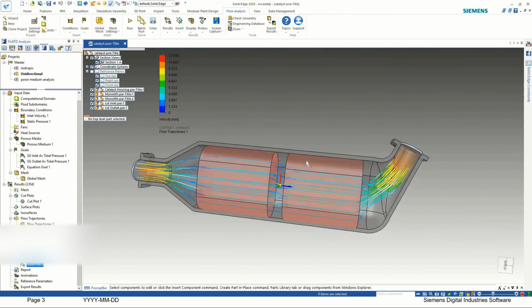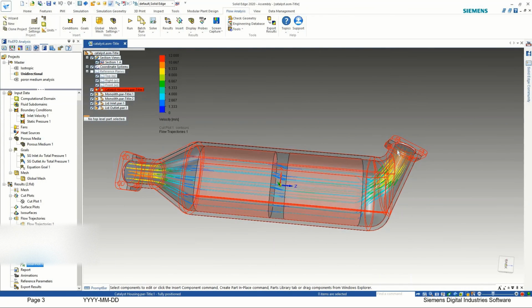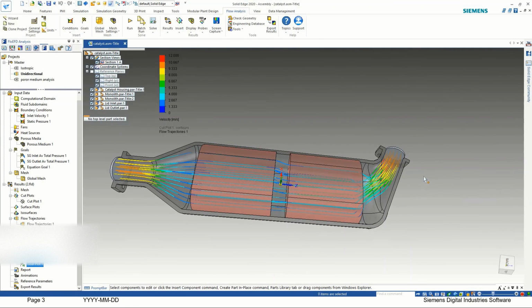And the best part is that with the help of fluid flow, that is inlet velocity, you get the pressure at this face also. So it will help you to get the pressure values to feed into the engine system, or you can say the motor and pumps system. So that is a very nice thing. So to get the rating, this kind of analysis will give you better answers, right? Because of resistance, how much pressure you need to apply to push the fluid out of the system.